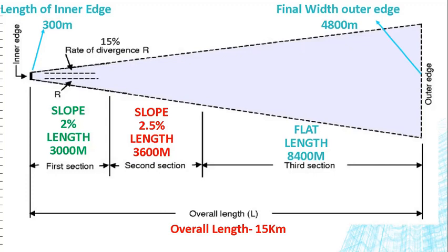And as we are aware, in most non-precision or precision approaches, the aircraft is coming with a 3-degree glide slope or the relative percentage. So this particular approach surface, an imaginary surface, is at maximum 2.5%. Above this, the aircraft can safely travel and land. It can make a safe approach towards the runway threshold.